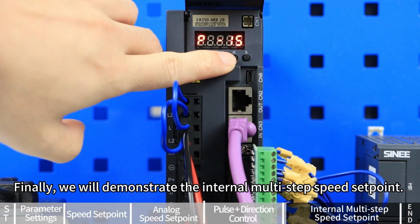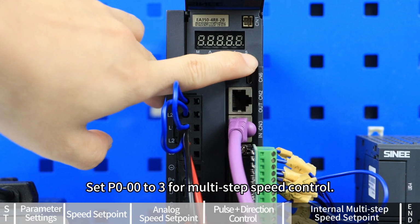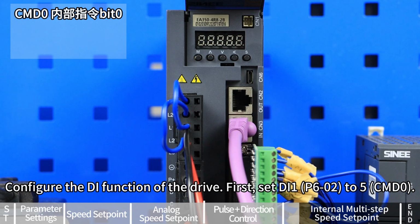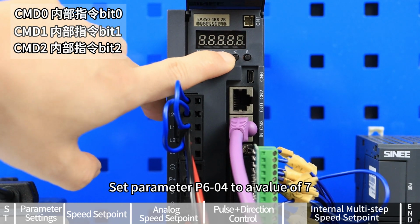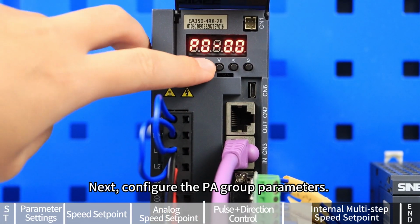Finally, we will demonstrate the internal multi-step speed set point. Set P000 to 3 for multi-step speed control. Configure the DI function of the drive. First, set DI1, P602, to 5, CMD0. Set parameter P603 to a value of 6, CMD1. Set parameter P604 to a value of 7. Next, configure the PA group parameters.